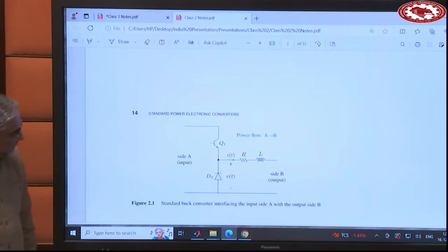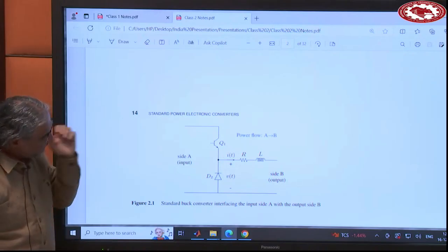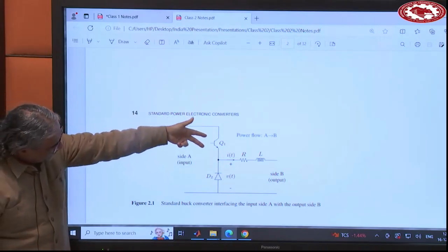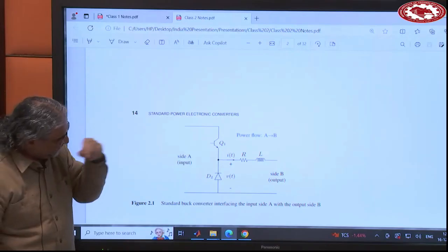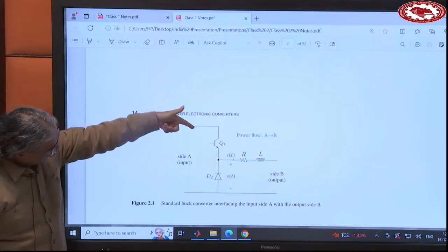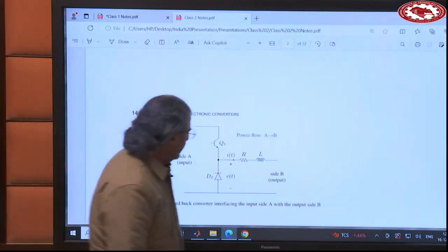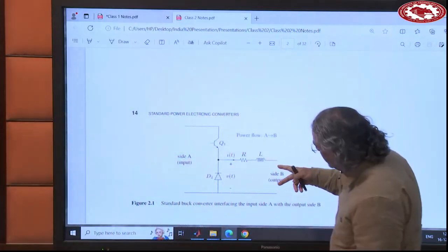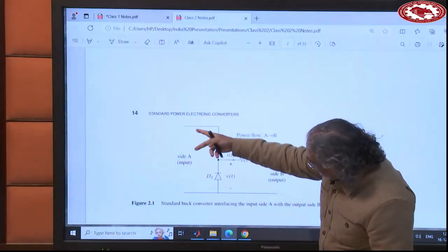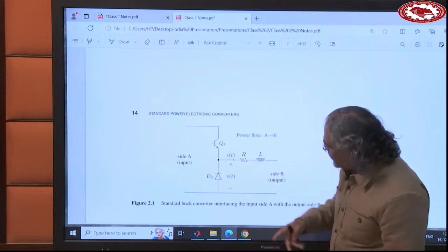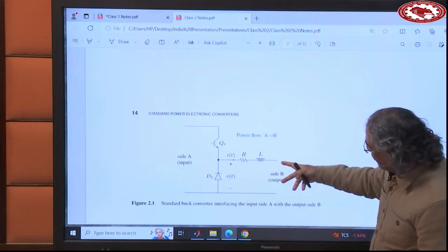So the way it works is, let's assume that you turn on this switch. So this terminal is now connected to this terminal point here, right? And let's assume this voltage, which is VA, across this diode, is larger than this voltage VB.